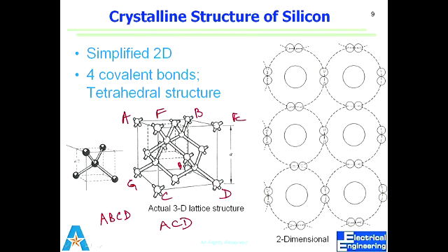Reaction. What do we need for a reaction? We need two atoms, right? Or molecules to come together. But the density of those atoms is different, so the reaction is going to be different. So whatever process we do on a wafer has different parameters and a different outcome for different planes. Do you agree till here? So that's why we need to know a little about planes.